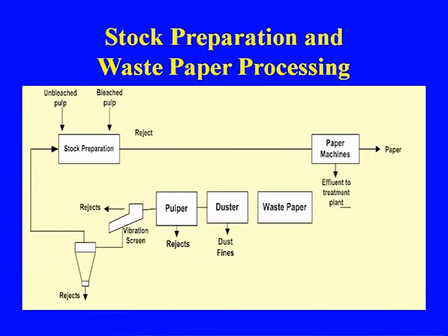After the dust remover, fines removal is there, then it goes to the pulper, and from the pulper it goes to the vibrating screen and centri-cleaning. Here centri-cleaning has a series of 3-4 stages, and finally after that it goes to stock preparation, where again the same activity is done as in the case of virgin pulp, and after that stock preparation, it goes to the paper machine.